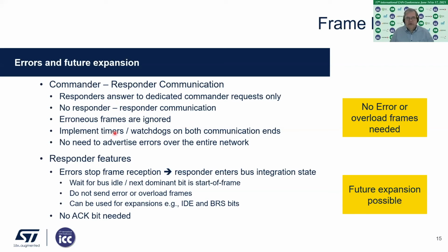And that means you can also implement timers, watchdogs on both communication ends, because the commander can check how long it takes until it gets an answer from a dedicated responder. And if the responder does not answer, then there's a communication problem. On the other side, the responder knows within what time frame it has to receive a communication request from the commander. And then you can implement a watchdog there as well. So you can implement this as a communication safety, and then the drivers can enter some sort of a fail-safe state, like turning on the rear lights, for example, if there is no bus communication.